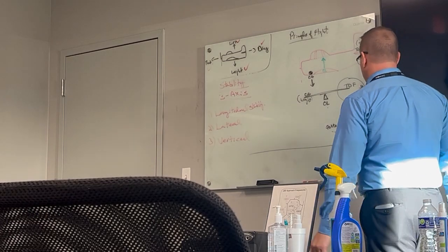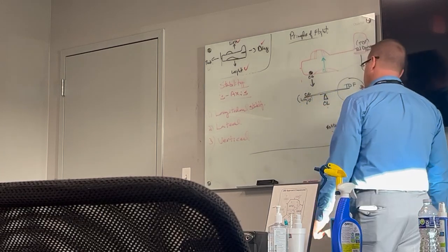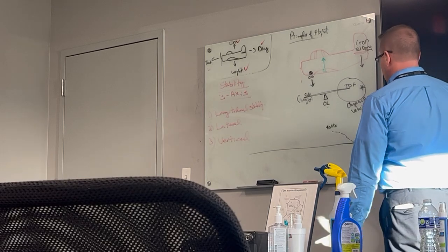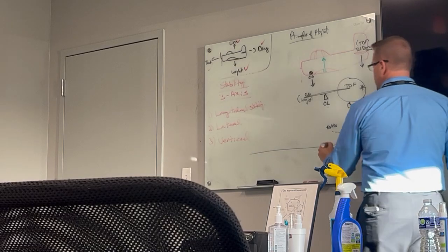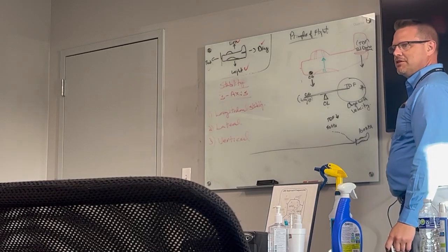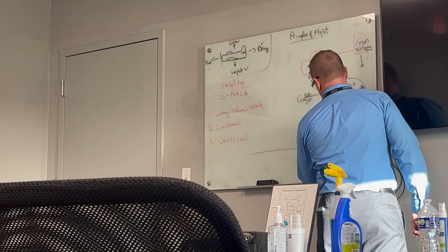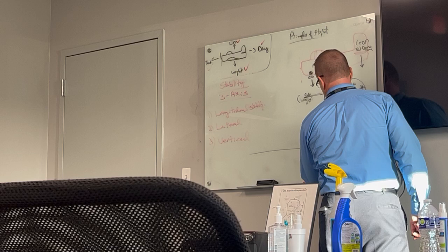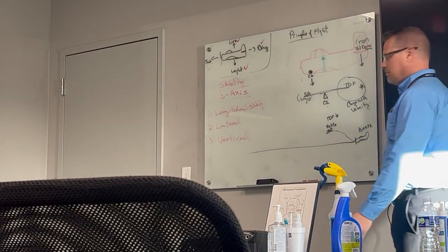Or we could do a little more, so we'll do 80. At 80 knots, is our tail down force more or less? Less. So if our tail down force decreases because our speed decreases, which is what we said here, change of velocity, that means the tail is going to be allowed to rise up, and the CG is going to take over and pull our nose back down.